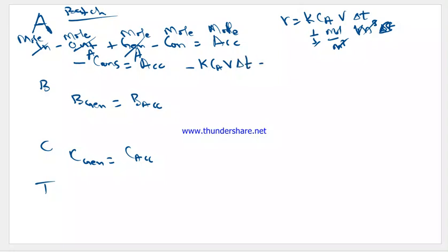This is equal to the change in mole of A with time. The change of mole of A with time is equal to d(CAV)/dt delta T. CAV is mole per meter cube times meter cube, which is mole. So that is the change in mole within the reactor, mole over dt times delta T. It's simply mole because delta T and delta T cancel in unit.